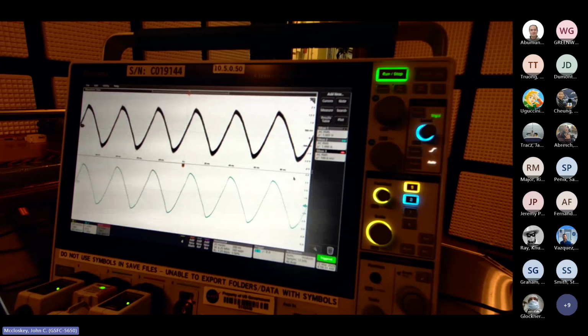You know, the scope will tell you if the waveform is distorted. It may not really change how you run the test, but it just gives you more visibility as to what the signal looks like. As we go up in frequency, I mean, you're really pushing the transformer pretty hard at 30 hertz. Even once we get up to 100 hertz, it's a bit cleaner.